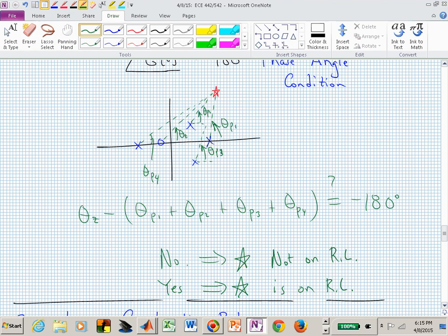We did it for angles relative to the real line before, but we can do angles anywhere in the z-plane from poles and zeros. And the poles are in the basement, that's why we're subtracting them in this transfer function, let's say g bar. And the zero angles are in the numerator, that's why we're adding those. Questions on that? Hypothetical question.